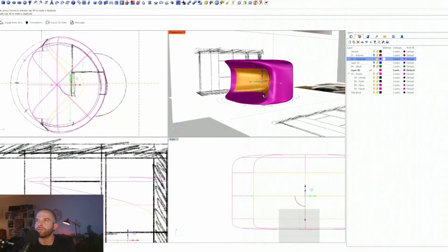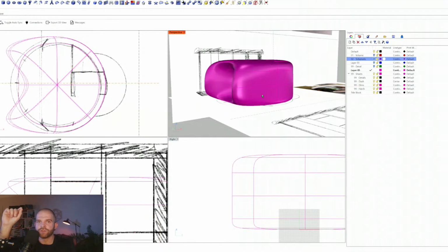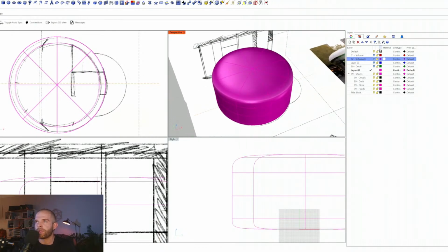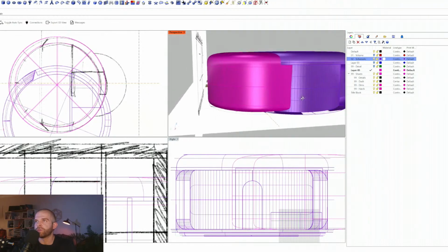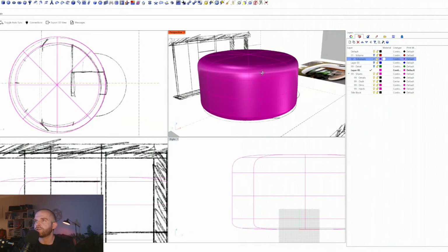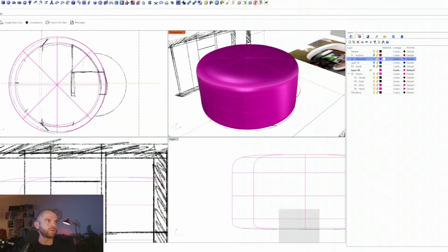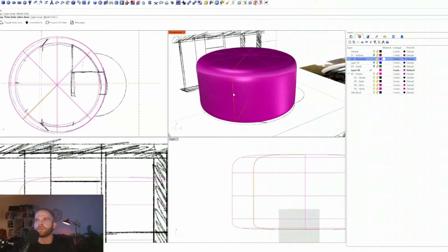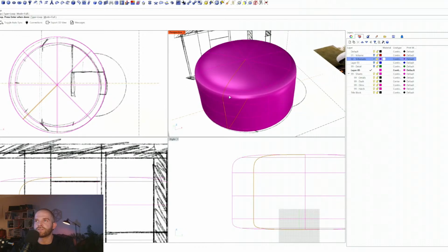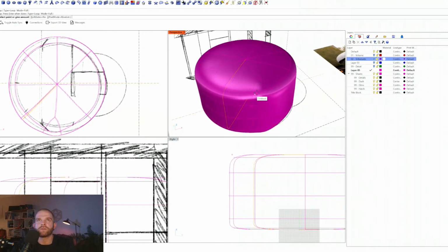So what we need to do is create more cuts on this geometry that will add more edges where we want them. So I'll undo. And essentially, bringing back this one, we want to cut in an edge for wherever the window would end on both sides. So we'll do InsertEdge. We'll type in InsertEdge for that command. Select from edge loop. So we have to pick an existing edge loop to add from. Let's say I want to do this one here, right? It's just this slice. I want to replicate this slice right in the middle. So I'll hit enter, and there we go. We're creating another slice there.